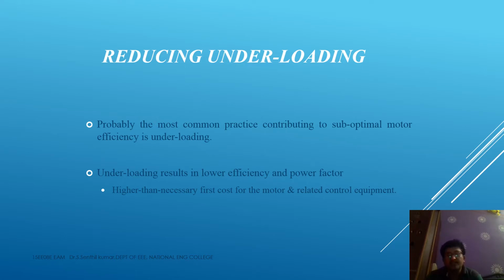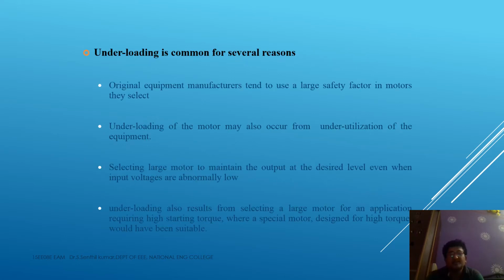So when choosing the rating and sizing, the load calculation should be done, and the exact sizing and rating of the motor should be chosen. Underloading results in lower efficiency and power factor. It is going to affect the motor performance. Now, some other common reasons for underloading.